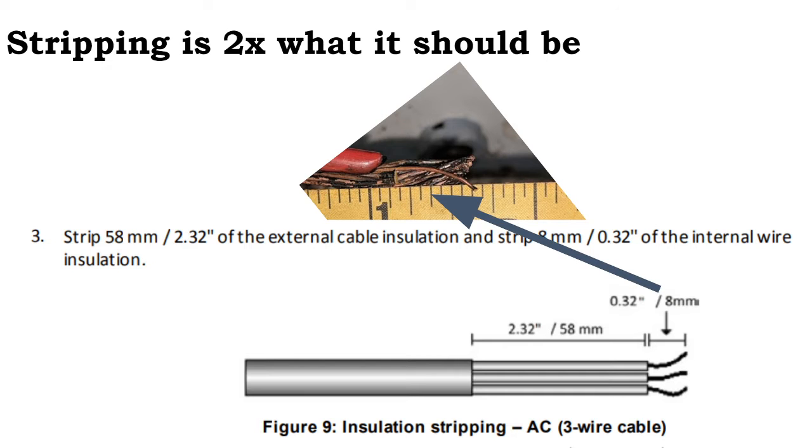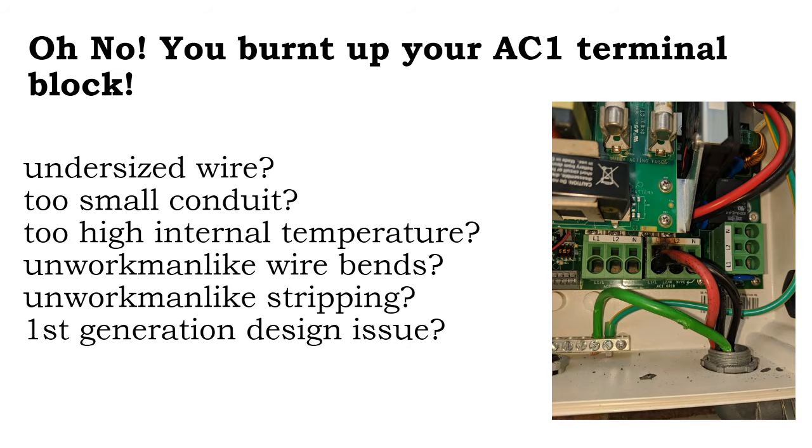They stripped too much of that off, and then these cables land on these inverters right next to each other, and there's not much space in these terminal blocks and computer boards for one power source and another power source. So this is where your project budget gets wasted by not using electricians to do your electrical work. Electricians will have more respect for good, proper workmanship and wire stripping to avoid these kinds of installation issues.